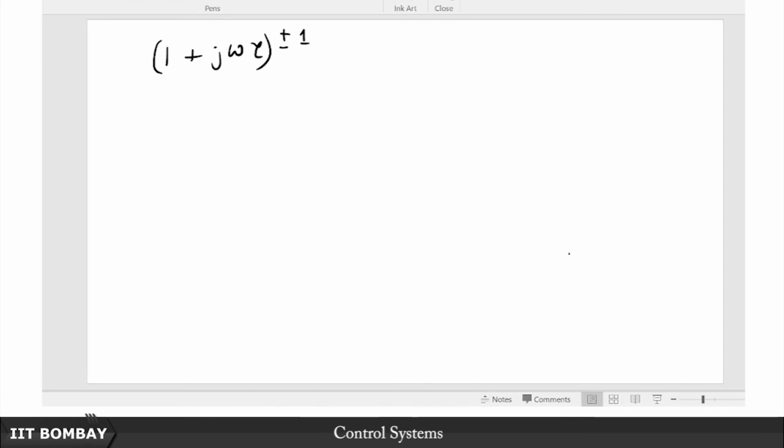So we shall see in general that ultimately, the asymptotic Bode plot gives us a lot of information, in fact most of the important information to a fair degree of accuracy. So you are not going to lose out on a lot of information by not drawing the accurate Bode plot as opposed to the asymptotic one. Therefore, we shall mostly concern ourselves with drawing the asymptotic ones, except for some very few points, maybe the break points or the so called corner frequencies. I will really not insist on making corrections.